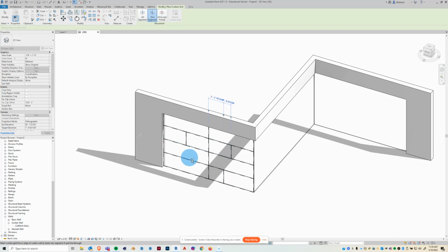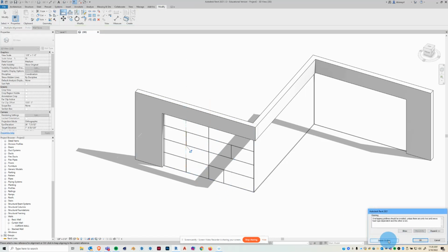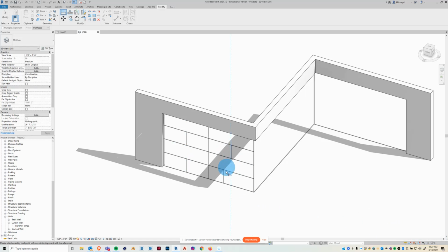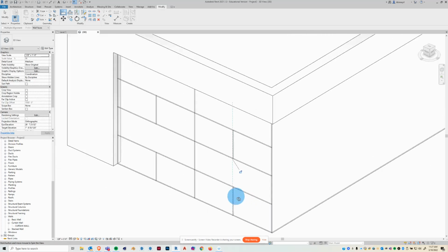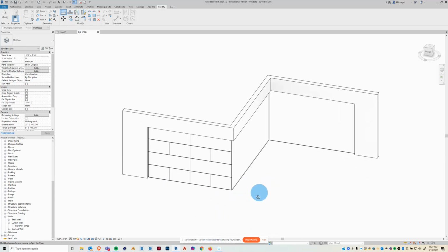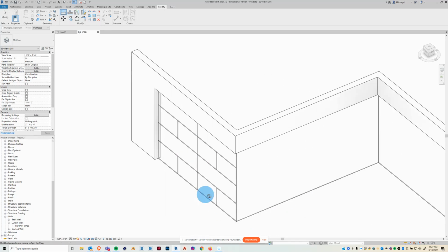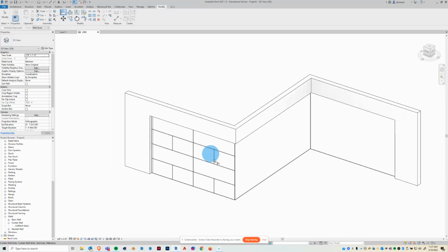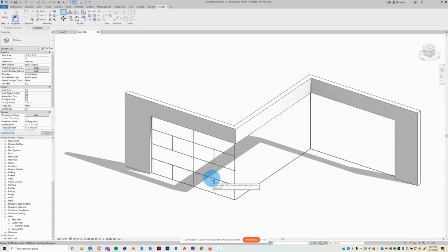And you can also, again, do this poorly. Then you can use your align tool. I'll say okay there, and okay there, because I'm moving one grid line to another grid line. So these are now on one grid line, and it deleted one of the grid lines. So I've designed this one out, but now I want to add some mullions.